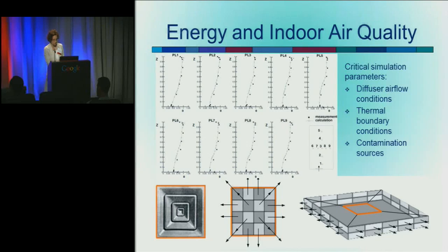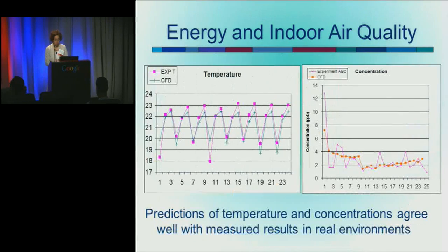And these lines that you can see here was some floor plan and vertical lines. The line here is simulated data, and dots are measured data for a temperature distribution. Incredible precision, considering how complex this airflow field is. And for those who are having some background in fluid mechanics, these are transitional flows at 10 to power 5 Reynolds numbers. Extremely hard to simulate properly.